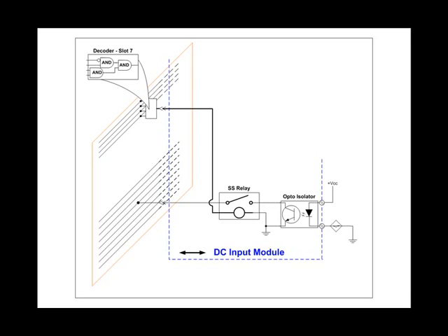One of 16 input isolation circuits connected to one of 16 common runs on the data bus, and the common connection between the control bus at the top of the diagram and the decoder. Remember, the decoder is physically a permanent item at each slot in the chassis. So the decoder is a permanent circuit at each slot and unique to that slot.